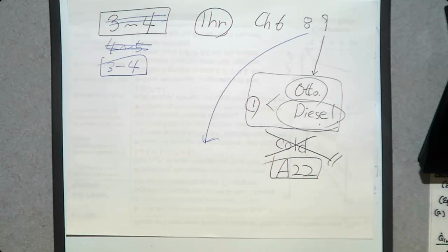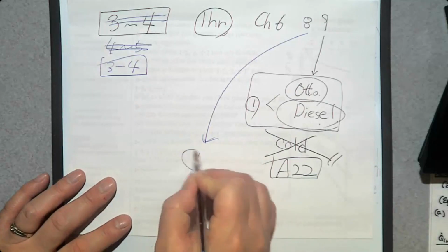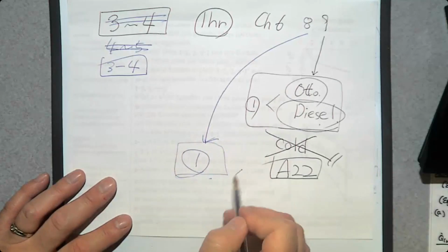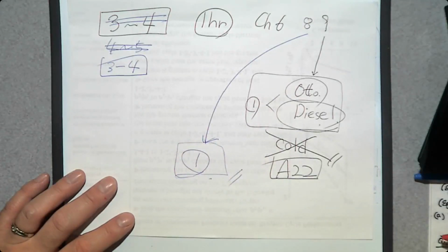Then what makes the last problem in the previous chapter hardest? Because it has 3 isentropic efficiencies, because the turbine has 2 stages. So you may see less than 3. Maybe 1 isentropic efficiency could be enough. So 1 problem from that. I don't have to explain anymore because we solved 2 problems.